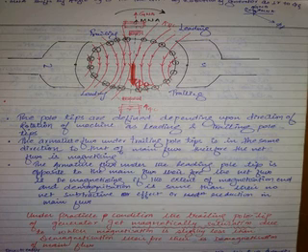Now, where is MNA? You know, this is MNA here, no doubt. But is the MNA the same in this particular case? No. Where is MNA? Definitely shifted by some angle theta, no doubt in that. It means in this particular portion, there is no zero now. The flux lines are moving parallel somewhere at this point, somewhere at this point, right? MNA is always making 90 degrees with the flux.